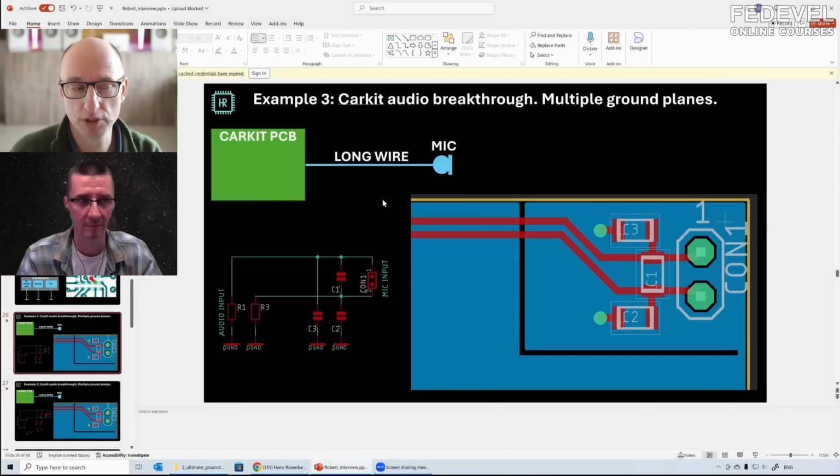Now that gives problems because if that gets into your analog electronics, it will demodulate. AM, if you put it in any transistor, FET, IC, it will demodulate. So you have to do something about this. Now, this kind of interference is common mode. That means that the interference current runs in the same direction on all wires. So if this is a 5-wire connection, then the current will go in the same direction on all 5 wires. Now, in this case, it's a 2-wire connection. So that interference comes in on this wire and on this wire. And well, the good thing to do is simply short it to ground.